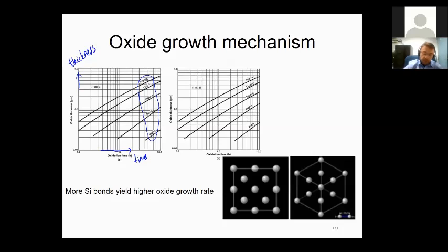So if you operate at different temperatures, I told you it's all chemistry dependent. So chemistry dependent means it's going to be temperature dependent too. Let's say you put the wafers in the furnace for 1 hour. Let's look at the output result at the end of the 1 hour. You always increase the oxide that you grow by elevating the temperature. So the higher the temperature, the quicker the oxide will be grown.